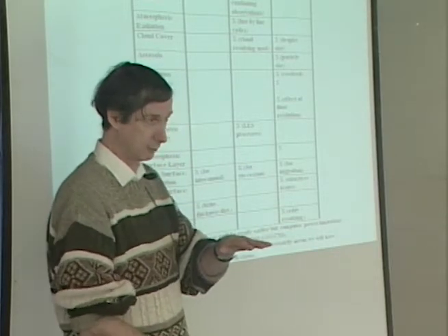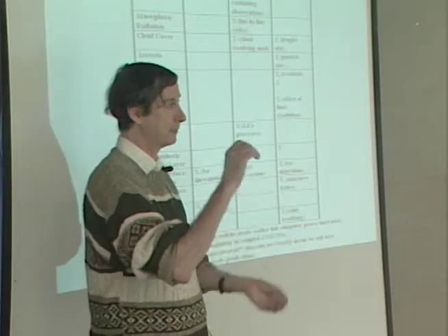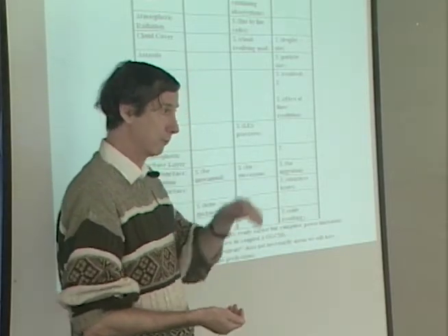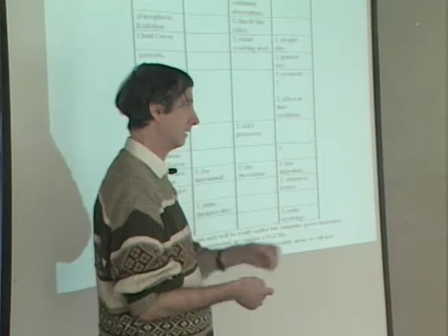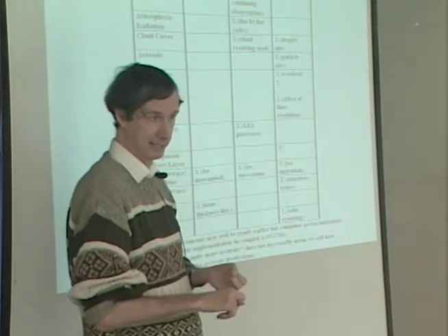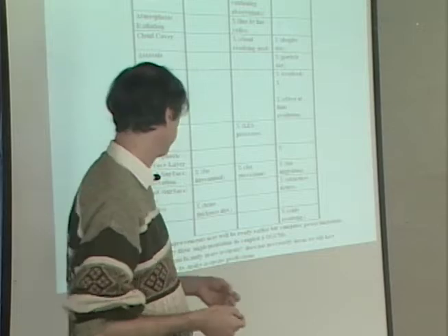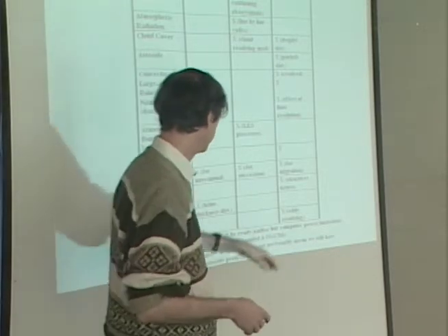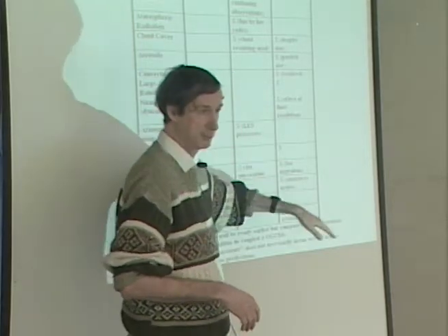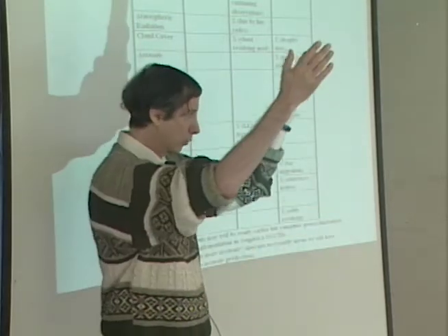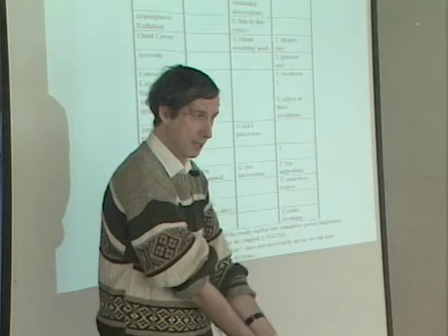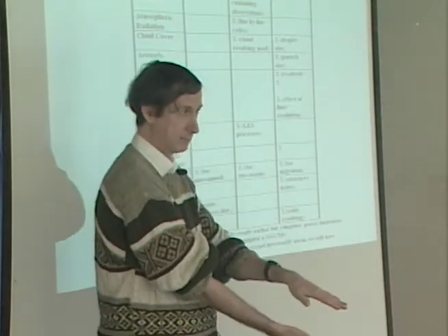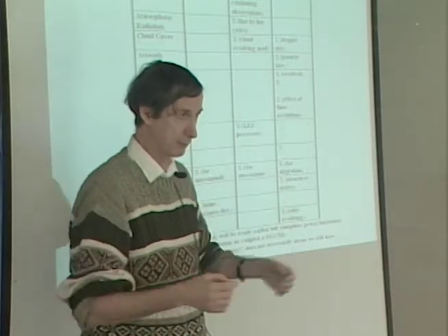Standard version is 6 soil layers, and moisture moves up and down based on texture discriminations, Darcy's law, with conductance coefficients based on whether it is sand, clay, or silt. Other people and other models assume that structure issues dominate vertical transport, like wormholes and root holes. So they have exponential decreases of this moisture conductivity with depth, sometimes the same everywhere all over the globe.